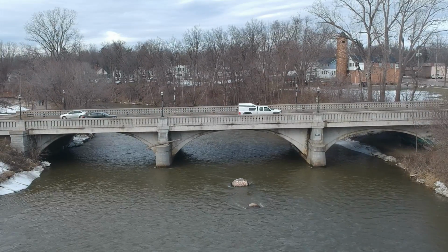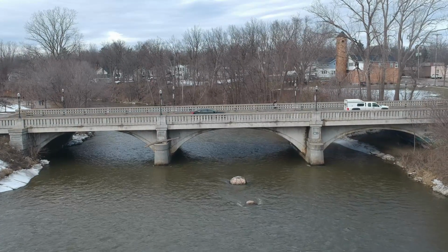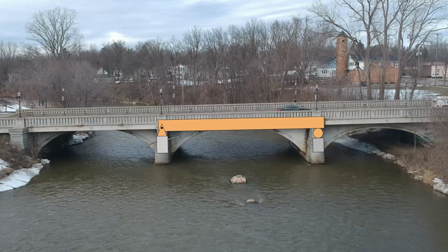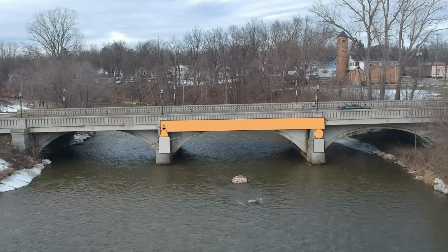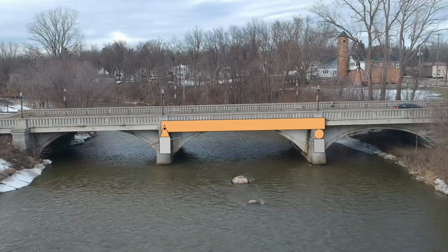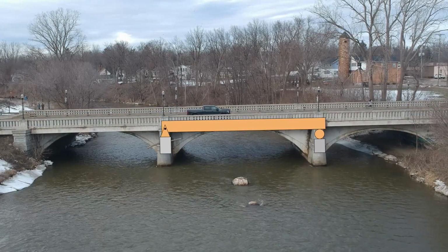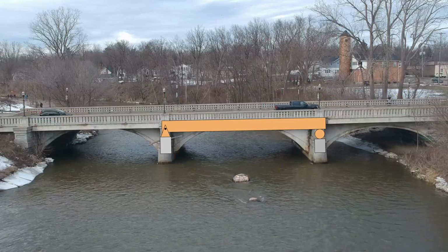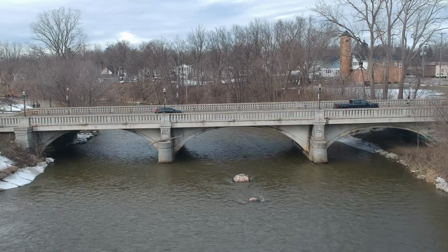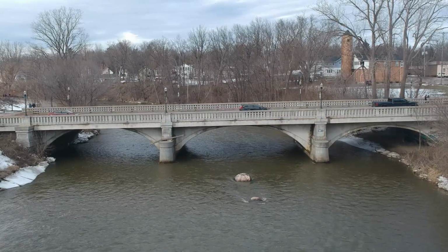For our analysis of the bridge, we simplified it into a flat beam of supports. To remove more complexities in the math, we only analyzed a portion of the bridge between two of the supports. This allowed us to use methods we have used in class to find the shear force and bending moment of the bridge under worst-case scenario traffic flow. These equations can then be used to find the resulting normal and shear stresses the bridge must endure.